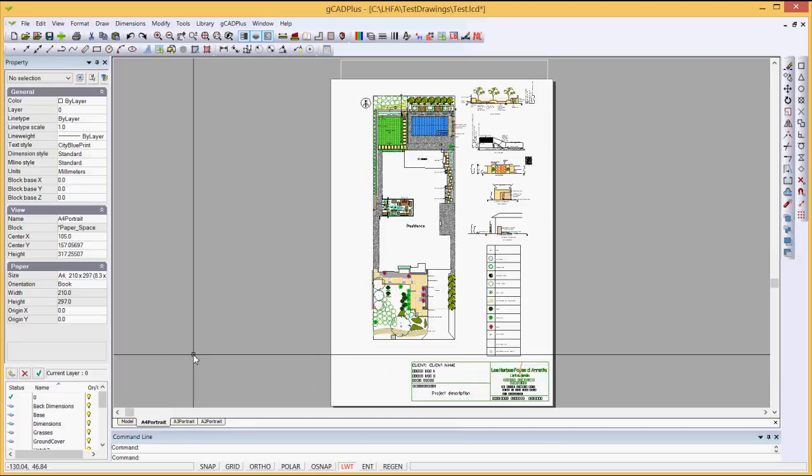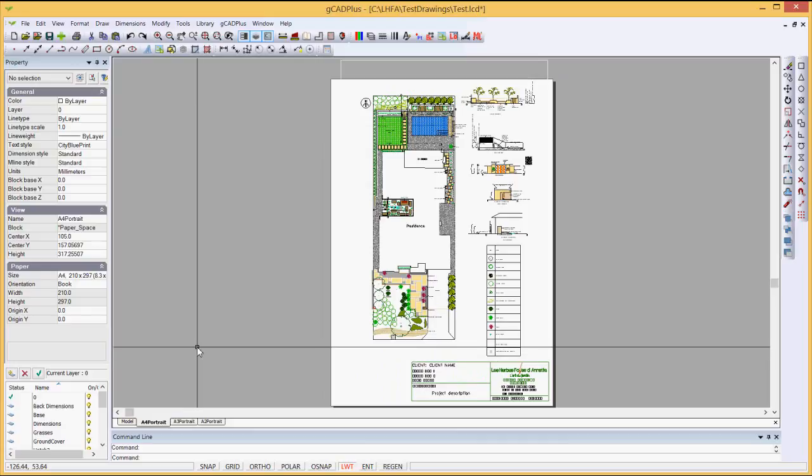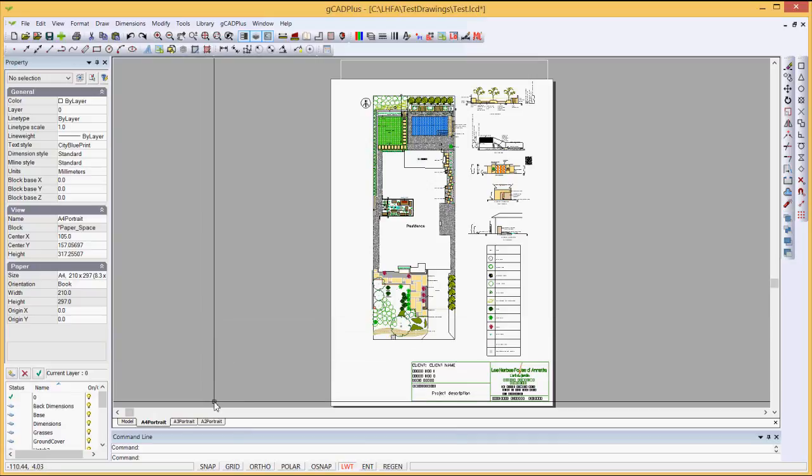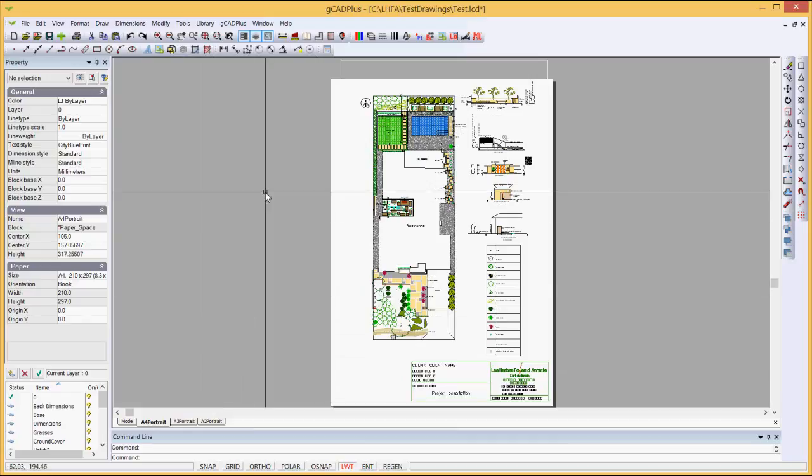My suggestion would be, looking at this, that we'll redesign the title block a little, and what we might well do is have two different template sheets, one for working A4 and A3 for maybe small designs, and another template sheet that might well have A4, A3, A2 and even A1. So we'll have a smaller set of layout sheets and a larger set of layout sheets to give us the versatility that I want, and then we'll put those and change and alter the path to the library.